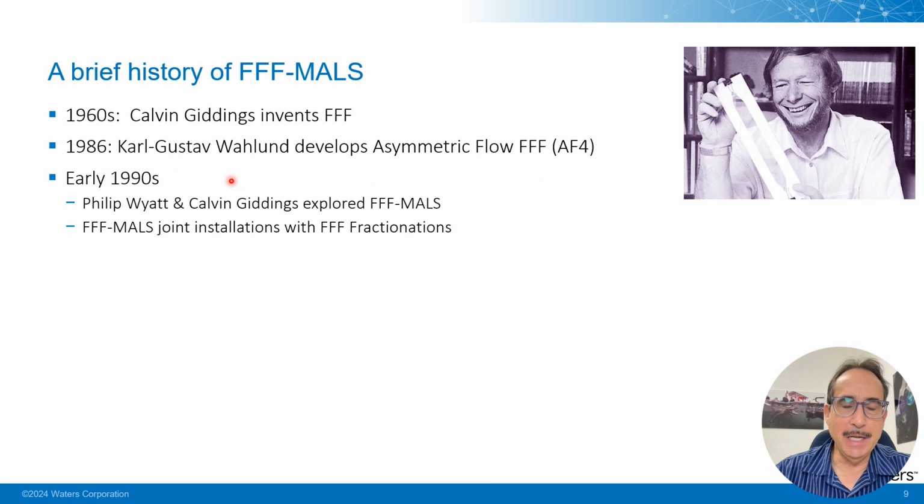In the early 1990s, Phil Wyatt, who was the founder of Wyatt Technology, started a collaboration with Kel Giddings to explore the coupling of FFF and multi-angle light scattering. Although the theory of FFF is quite well developed and understood, it ignores things like interactions on the membranes and the three-dimensional effects that happen in the corners of the cell. And so if you use the elution time and the FFF theory to compute back the size, you are limited